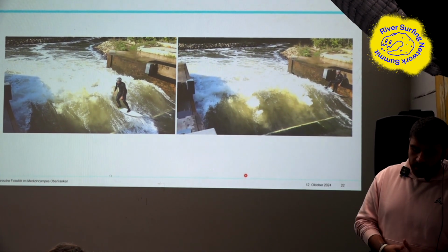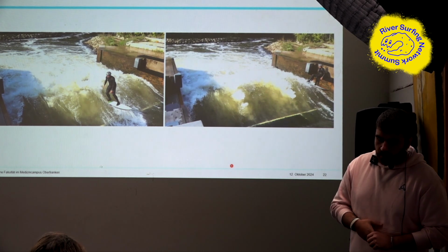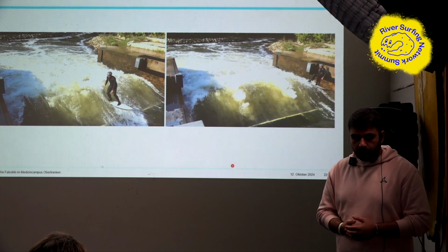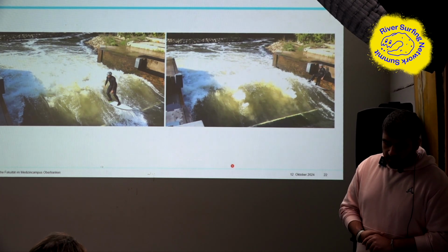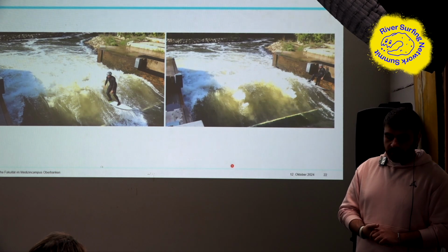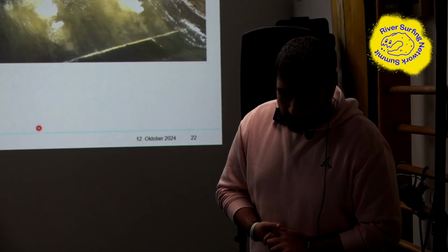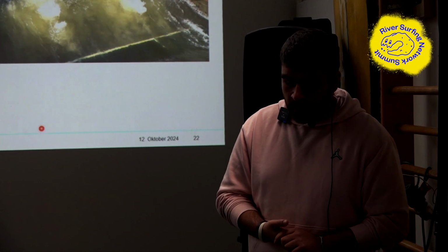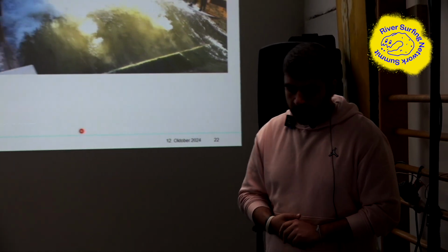So the modification with our chicane now allows the operators of the wave to operate the wave with more than 8.5 cubic meters per second without the risk of being pulled back into the wave. Even for first-time surfers, now a flow of 9.5 cubic meters per second is possible without any safety concerns or little safety concerns, which also leads to a bigger wave, hence a bigger surfing area.